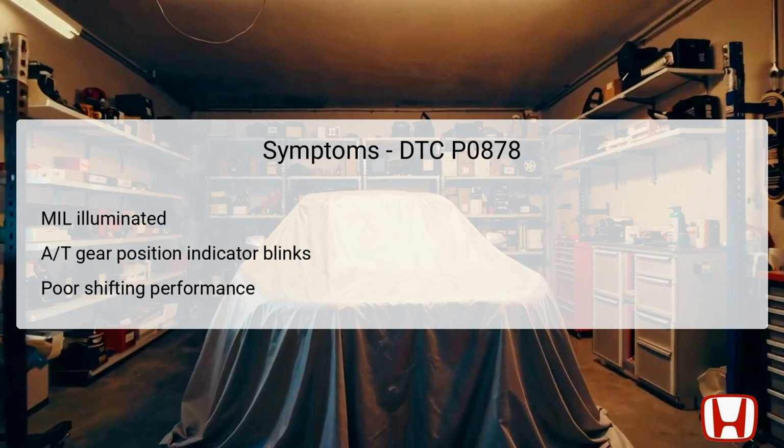Another common symptom observed is poor shifting performance, including hard or delayed shifts, specifically during the shift into fifth gear. These symptoms collectively suggest that the transmission fluid pressure switch D is malfunctioning, warranting further diagnostic procedures to determine the root cause of the issues.